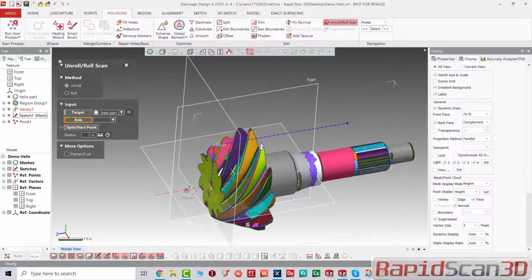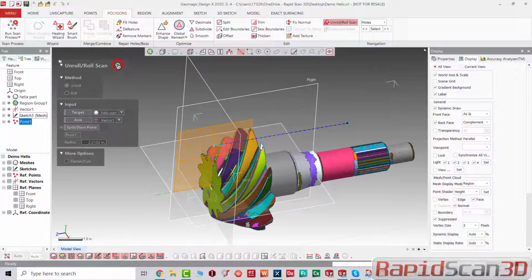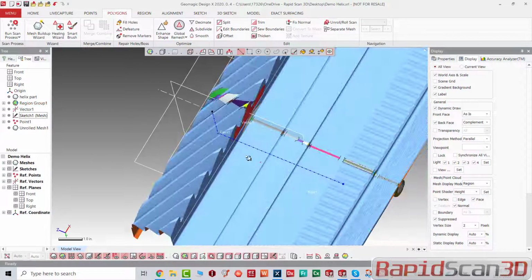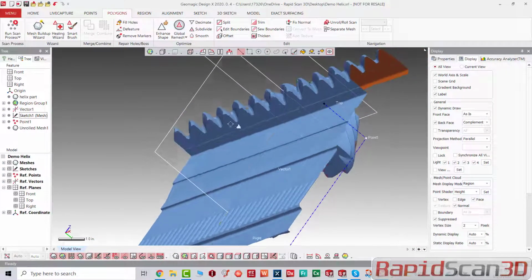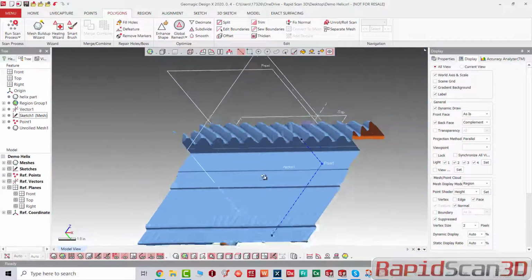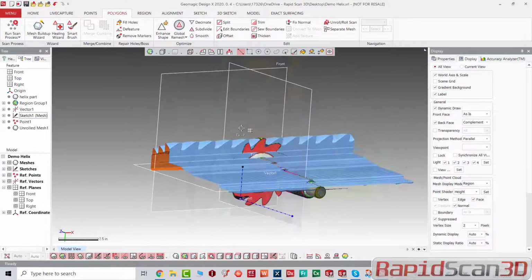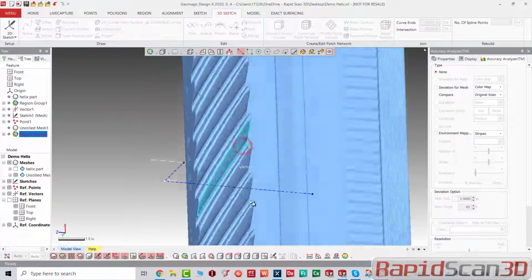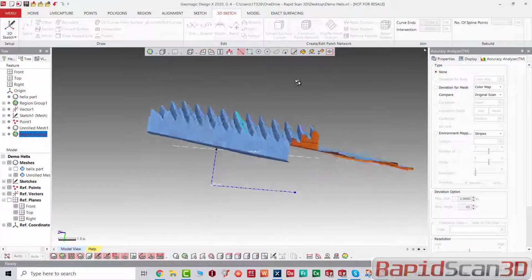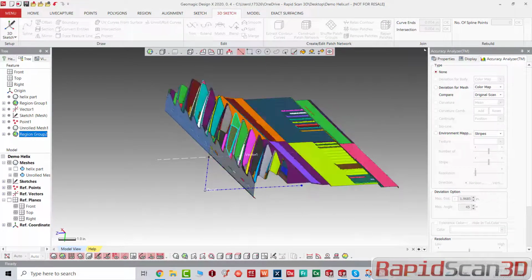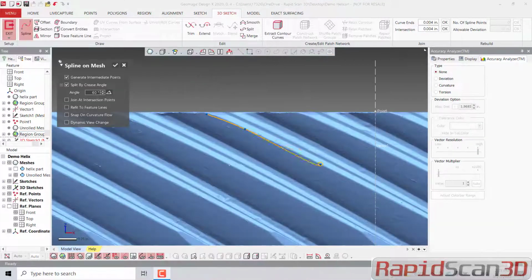So let's click on the axes and then we're going to click on the split point, and that creates an artificial plane, and then it's going to create the flat mesh. Now if you look at the mesh data, we can see it has a little curvature. It has a radius. Now I'm going to hide. If you look at the left side, it has a helix part and an unrolled mesh. So this is an unbelievably powerful tool if you have a pattern around the curve.